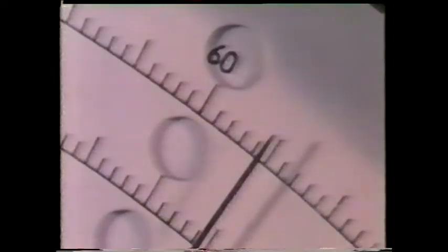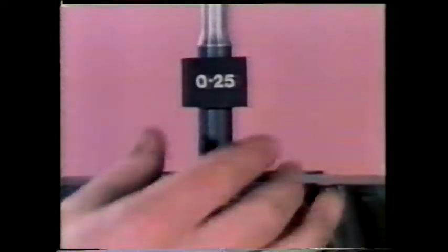That fractured at 61 kilonewtons. 0.25% carbon steel. Let's see what force is needed to pull this one apart. This test piece has the same dimensions as the previous one, so by comparing forces, we can compare the tensile strength.